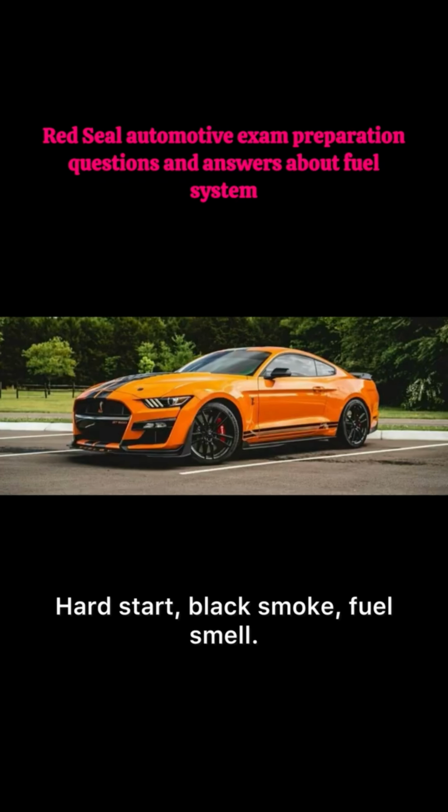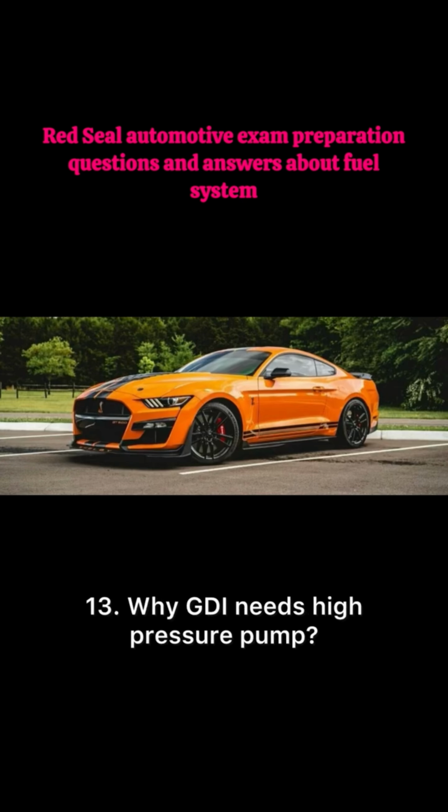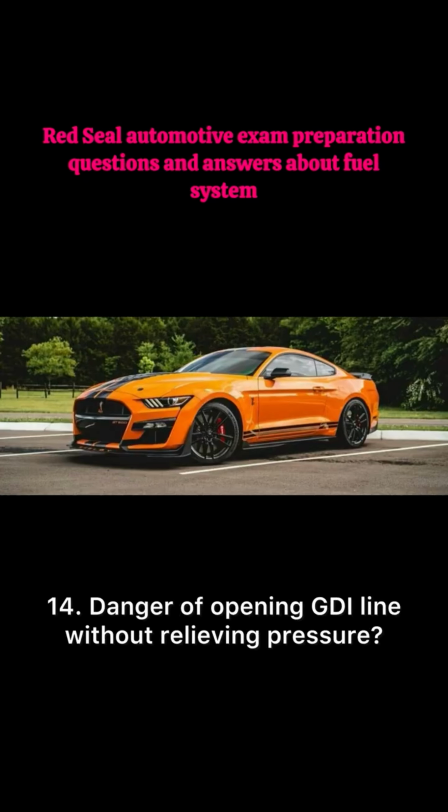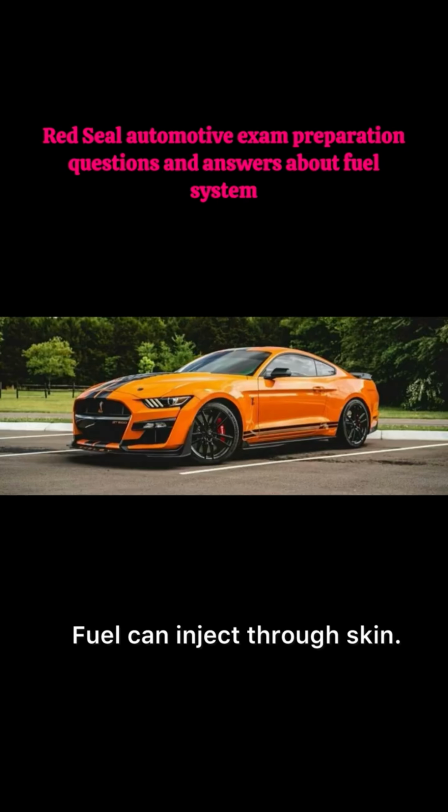12. Fuel tank pressure sensor job. Monitors tank pressure for EVAP tests. 13. Why GDI needs high pressure pump. Injects into cylinder, must beat compression. 14. Danger of opening GDI line without relieving pressure. Fuel can inject through skin.